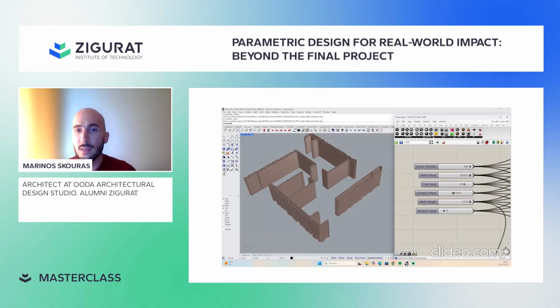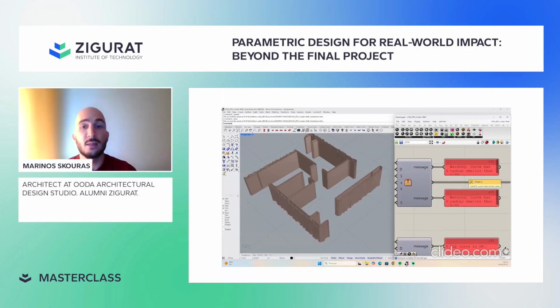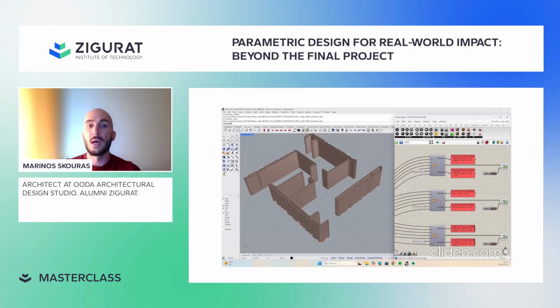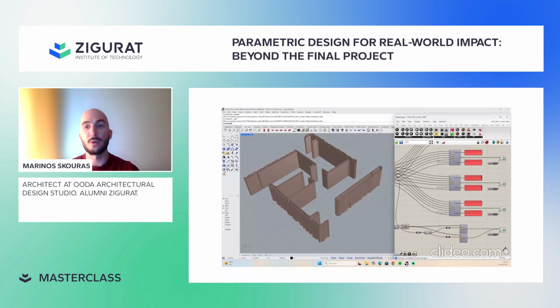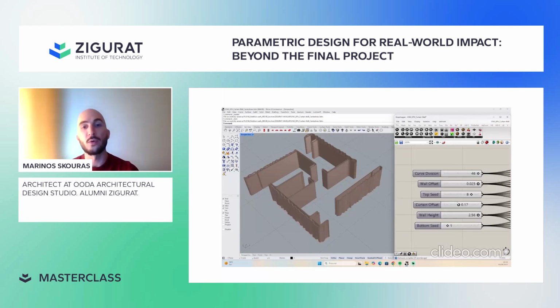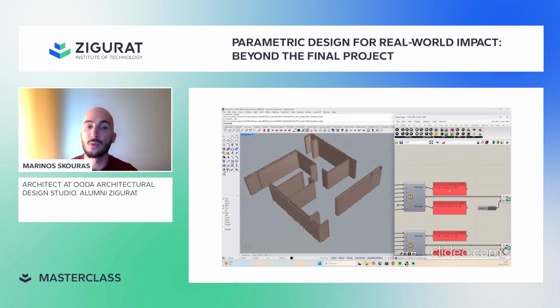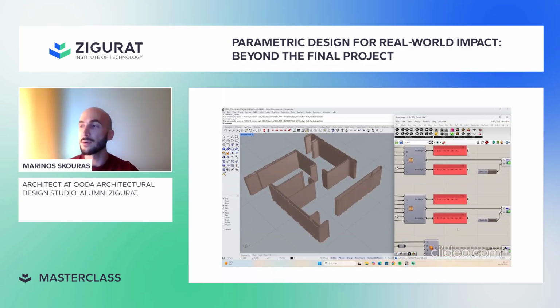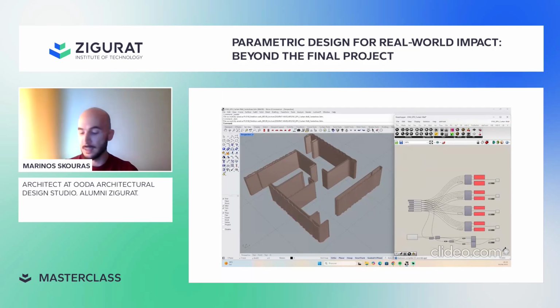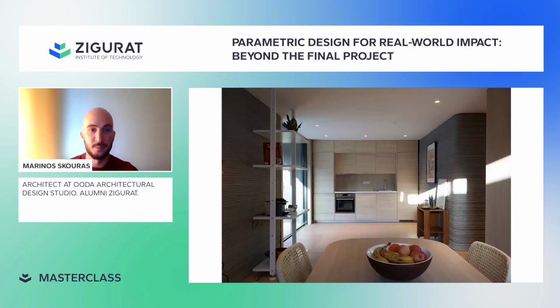One technical limitation was that the curve radius couldn't be smaller than 5 centimeters, as the printer couldn't handle tighter curves. So I wrote a Python script in Grasshopper to flag any violations, allowing for quick adjustments and validation. Right now, you see that I got an error message saying that the radius is smaller than 5 centimeters. So I went back to adjust the parameters until I got the message that all the curves are okay. This is a sign that I can move forward.